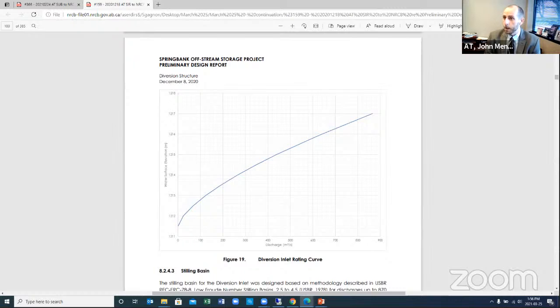I will note, as you mentioned, the bottom of the wall is 1215.5. What you will see, though, is that this curve is not set immediately at the wall. It is upstream before you have the influence of drawdown into the structure and through it. So when we tested this in numerical models and in physical models, what we observed was that at the breast wall and at 600 cubic meters per second, the water surface elevation doesn't touch the wall.